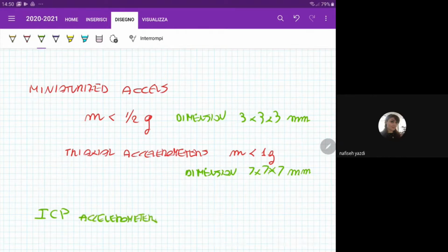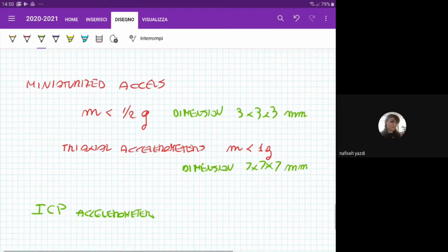That are included inside the accelerometer a small integrated circuit that is transducing your electrical charge directly from the PZT into an output tension, so that you can plug the output cable from the accelerometer that is in volts straight into your measuring circuit that is covered to measure volts.